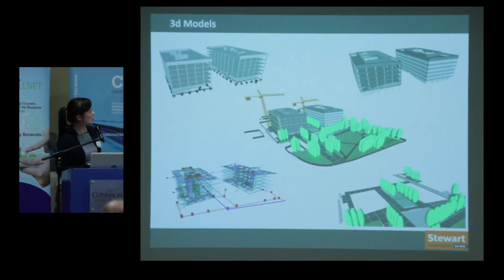Next one, so on this project we have different disciplines produce their models, which are linked by using shared coordinate system. So you're looking at the structural model, architectural, mechanical and landscape. Those are linked together, and in the middle you have our main contractor, so basically site setup, cranes and compound to the back of the site.